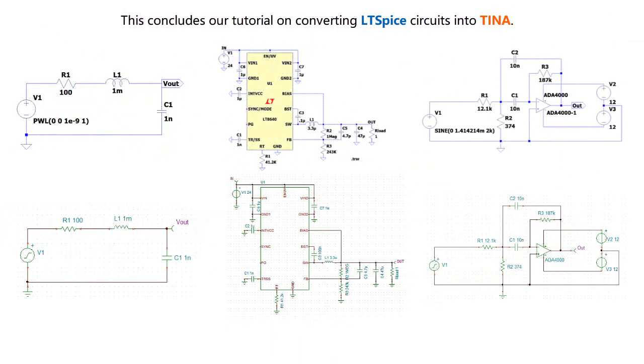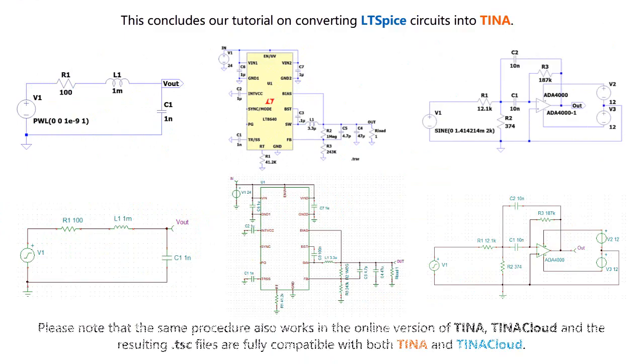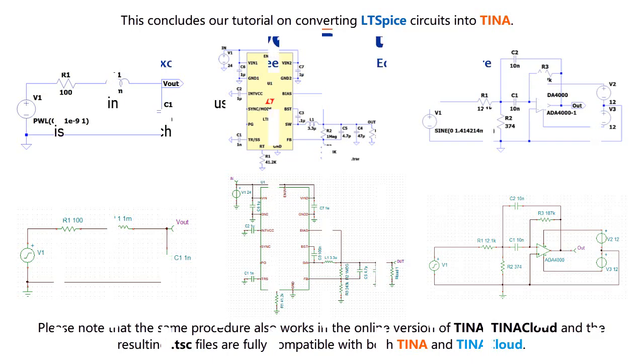This concludes our tutorial on converting LTSpice circuits into TINA. Please note that the same procedure also works in the online version of TINA, TINACloud, and the resulting .tsc files are fully compatible with both TINA and TINACloud.